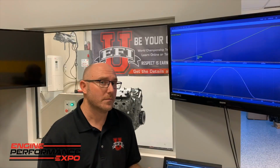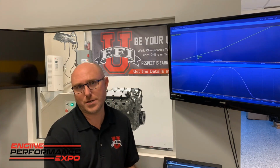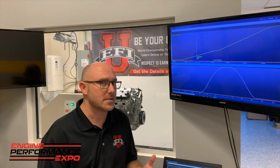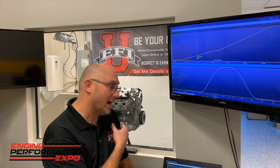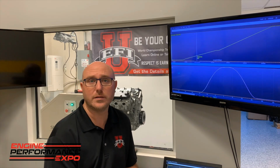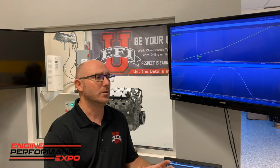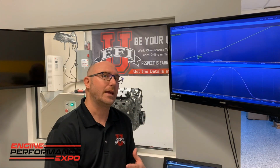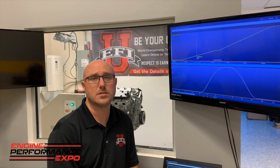Now here's the cool part. Since we didn't have a real piston and connecting rod and an actual crankshaft in there, it means that we don't have combustion, so we don't need things like the water jackets to be full of water. Since we don't need the water jacket, then we really don't need the side of that cylinder wall. So what we typically do is we'll have a dedicated test block, and we'll set it up in the middle, cut a big hole in the side of the cylinder, and that gives us access to the cylinder while the engine's basically running under simulation.